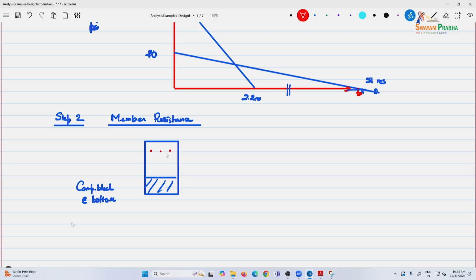So let's consider here, we'll ignore the compression block reinforcement. Again, you can get fancy and definitely do all of that, but we'll keep it simple here. These are 4 number 6 bars given. This effective depth I have not given you, but the effective depth is 16 inches. The width of the roof beam is 6 inches.